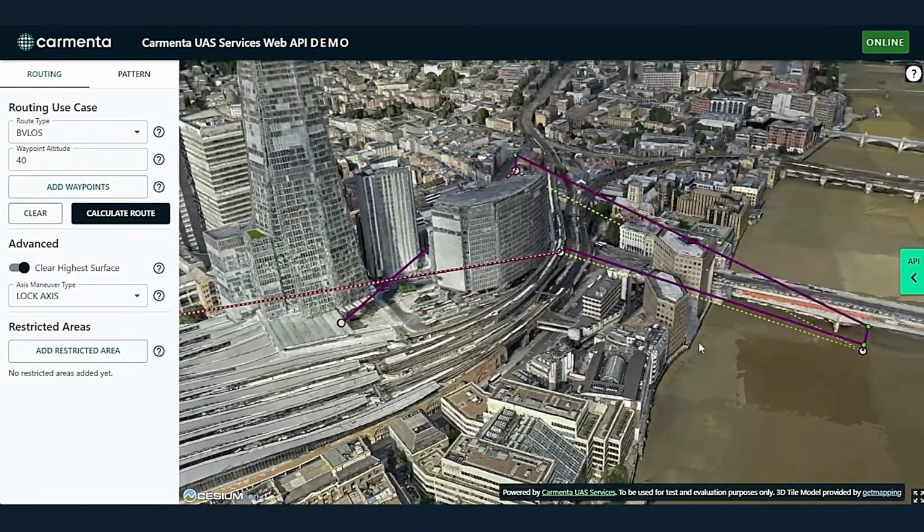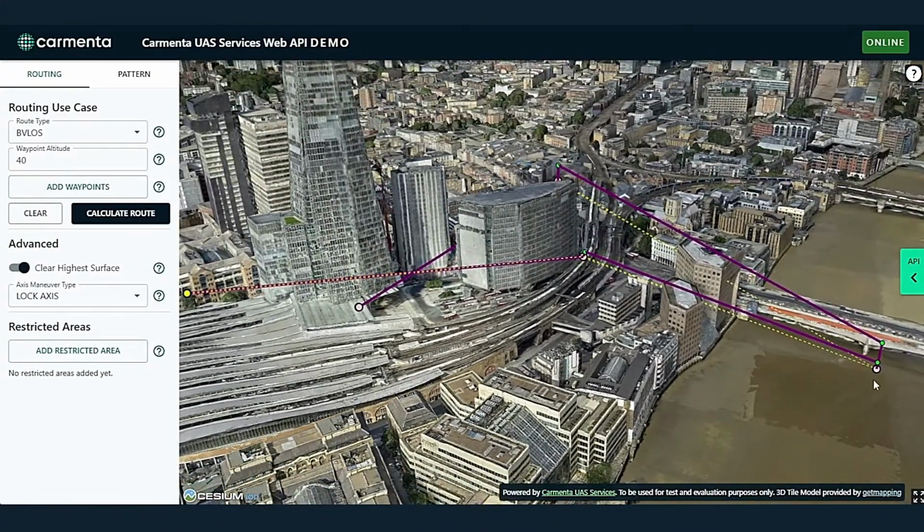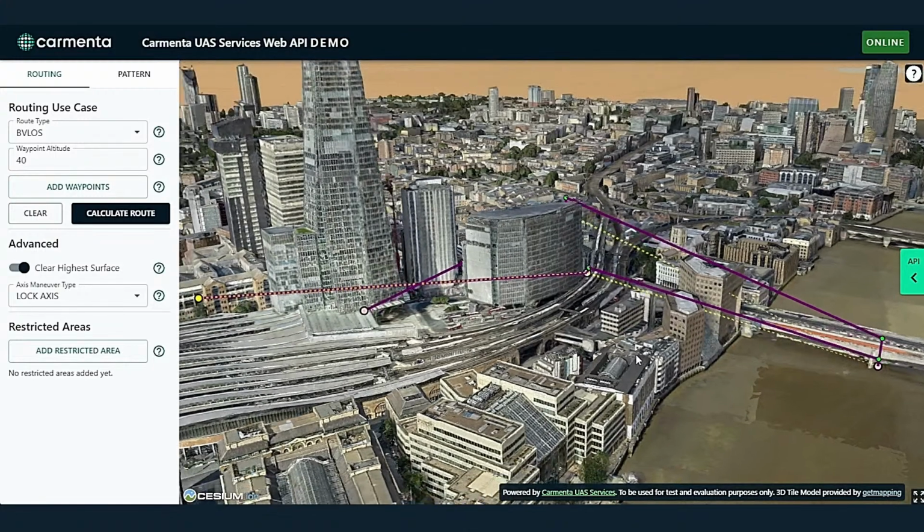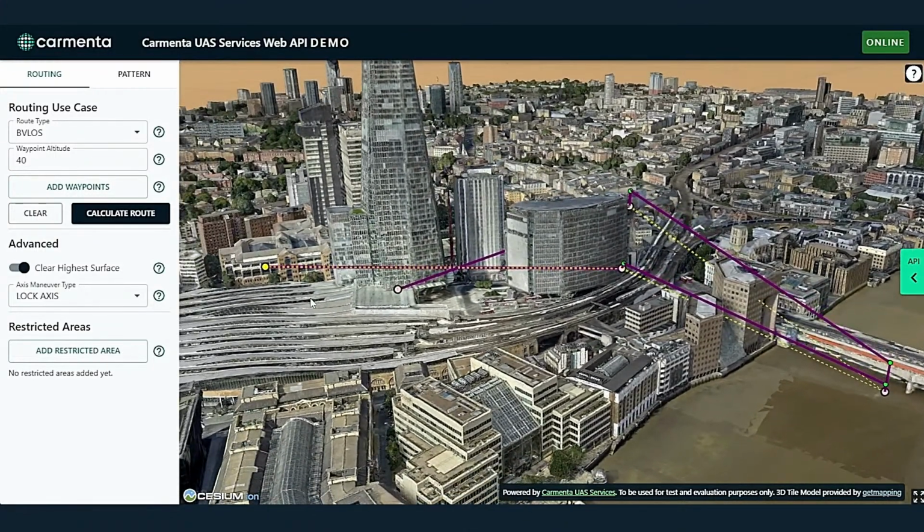So in this particular route, by default, what we actually do is traverse on a single axis at a time. So we'll move on the XY or latitude longitude axes independently or separately of the Z or altitude axes, and that's simply just the default, just for drone compatibility, just in case your drone can't fly 3D for whatever reason, without passing that parameter. So it's almost a fail-safe to support all rotary wing drones.